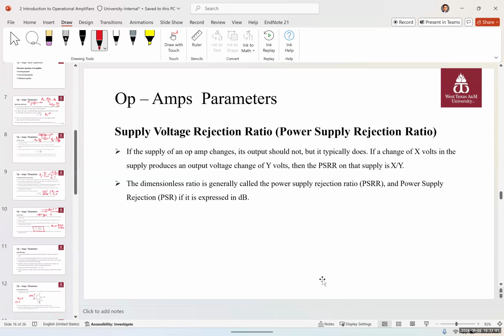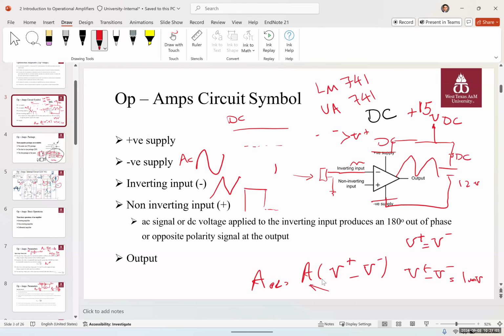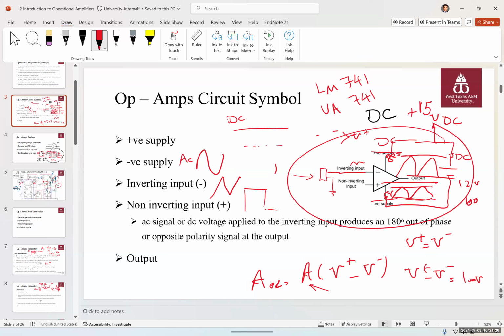So what happens is after a while, the voltage drops. Because the battery is depleting, it goes down to 10 volts. Now the output signal, instead of being this large, it's going to be half this size. So instead of having 10 volts peak to peak, or 8 volts peak to peak, you have 5 volts peak to peak. And that cannot turn on the light. So that's not good at all. Okay. So we have to design a system in which when the supply voltage drops from 12 to 10 volts, we will still have a constant output in the system.